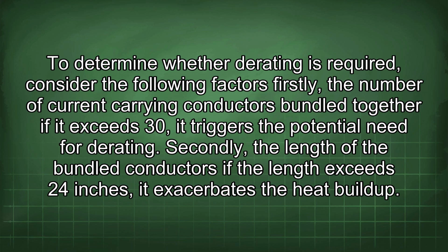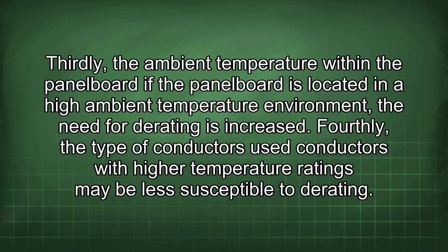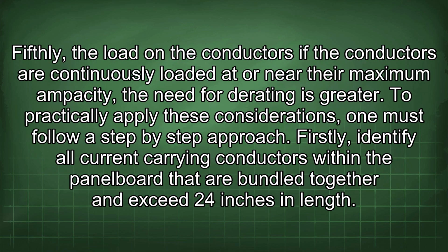To determine whether derating is required, consider the following factors. Firstly, the number of current-carrying conductors bundled together. If it exceeds 30, it triggers the potential need for derating. Secondly, the length of the bundled conductors. If the length exceeds 24 inches, it exacerbates the heat buildup. Thirdly, the ambient temperature within the panel board. If the panel board is located in a high ambient temperature environment, the need for derating is increased. Fourthly, the type of conductors used. Conductors with higher temperature ratings may be less susceptible to derating. Fifthly, the load in the conductors. If the conductors are continuously loaded at or near their maximum ampacity, the need for derating is greater.